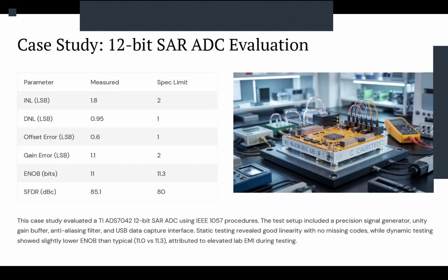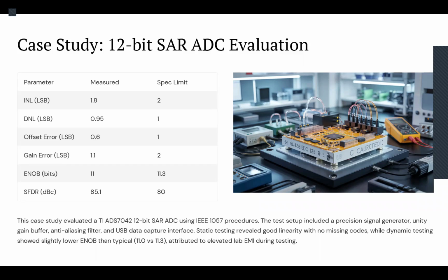When you want to do the test, what's important, as we said, is that temperature is one of the important parameters. We know that when an electrical system works, the temperature rises because of the losses. So before we measure, we need to let the temperature stabilize, so the system warms up. It takes approximately 30 minutes, but you need to make sure that the temperature is stabilized.